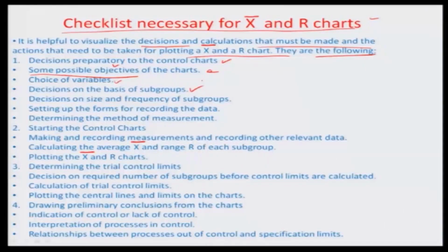The idea is, once you have started recording some observation, it has to go on for at least a few numbers before you stop recording on that particular event period, and then go for the next event period. So there are different event periods like this in the whole production shift. It may be a group of 5 observations. These 5 could be, let us say, every second or third item on the production line. So you are recording every third item 5 times, let us say the subgroup size is 5, and then waiting for a few hours, and then again recording after some more hours the same every third item 5 times again.